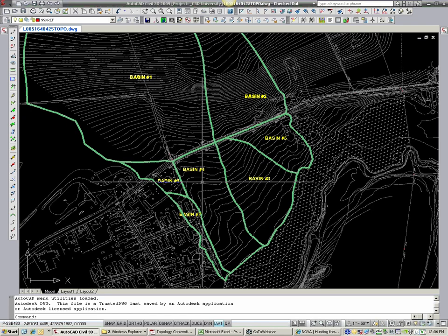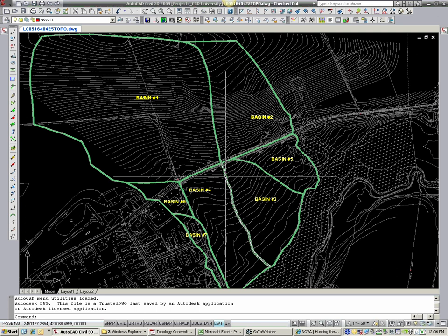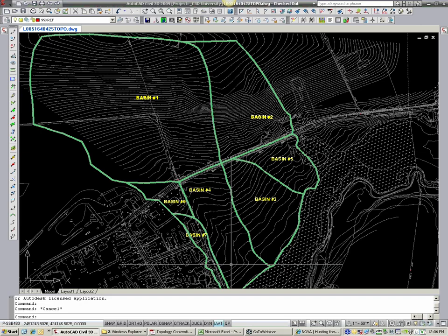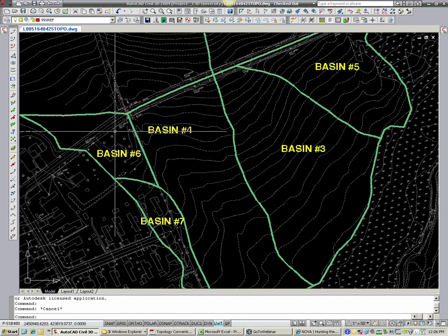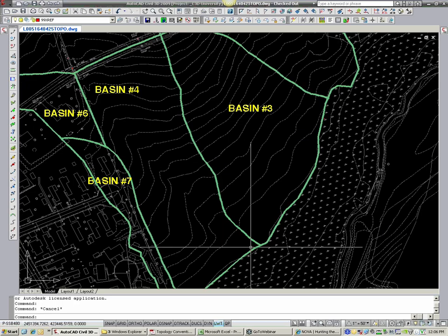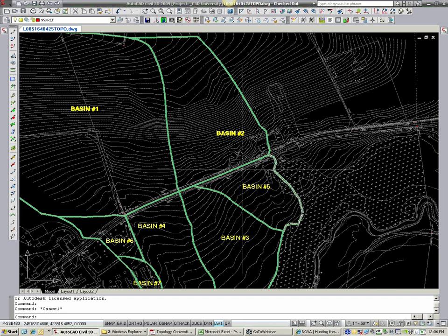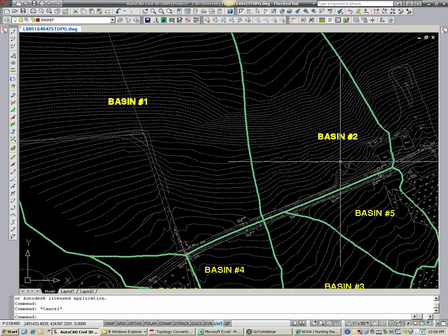Today we're going to do the pre-post stormwater. And I'm going to shoot through pre here just real quickly and showing you how to set up a topology. So you can see on the screen, have some line work here that I outlined my pre-development drainage map. We're developing this site, the area of the site right down through here, through Basin 4, 3, and 5. So I've split it up. We have a channel coming down through here and another channelized section here, and this all goes into the wetlands, just straight feed into the wetlands and so on and so forth. Got some bypass area coming through a culvert here in the road, and same thing over here.